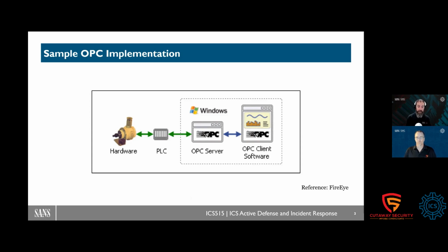For the Classic, there are 3 different implementations. One's data access, where you're looking at current time tags, parameters, values. What is the value of that pressure transmitter? Is that valve open or closed? Is the pump running or stopped? And then we've got our historical data access. What was the level of that tank over the last 2 hours or 2 days or 2 years, potentially?